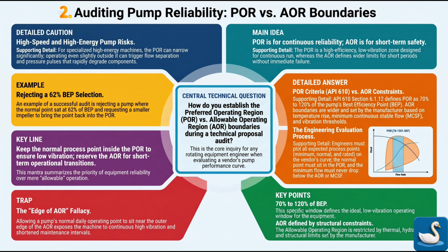Allowing a pump's normal daily operating process point to sit near the outer edges of the AOR exposes the machine to continuous high vibration and asymmetric hydraulic loads. But the manufacturer says it's allowable. While the manufacturer states the pump will not fail immediately in the AOR, running continuously in that zone will significantly shorten your maintenance intervals. Mechanical seals will degrade exponentially faster, and bearing life will be severely compromised.